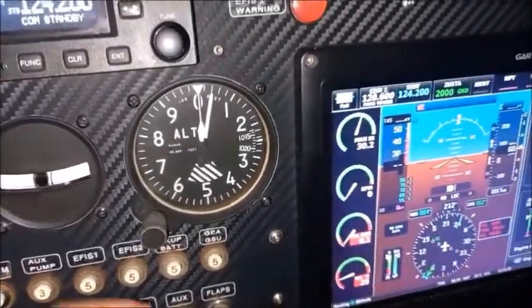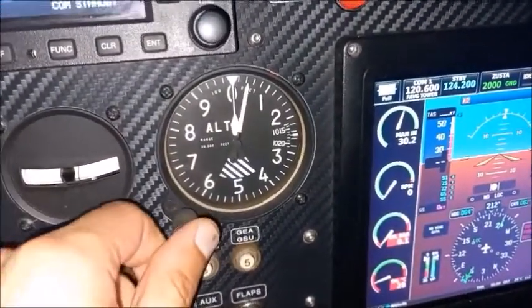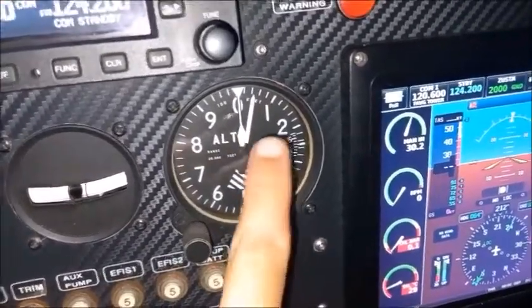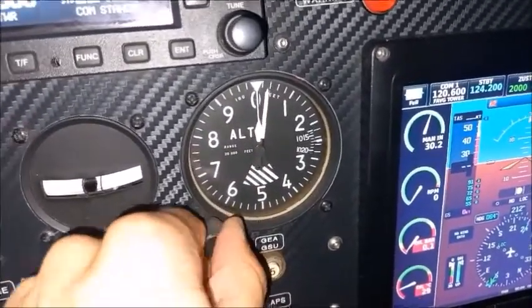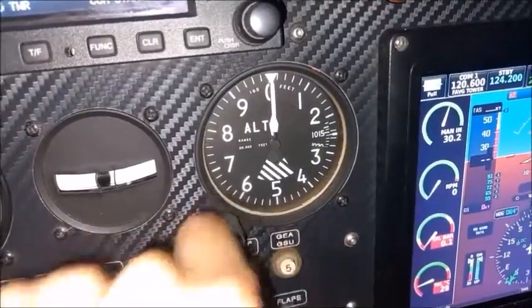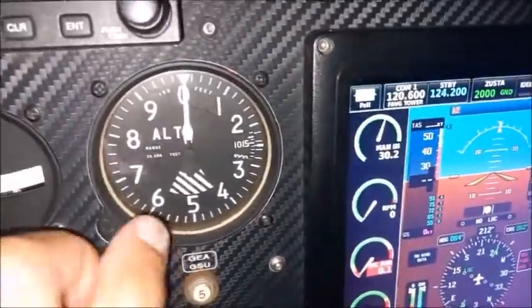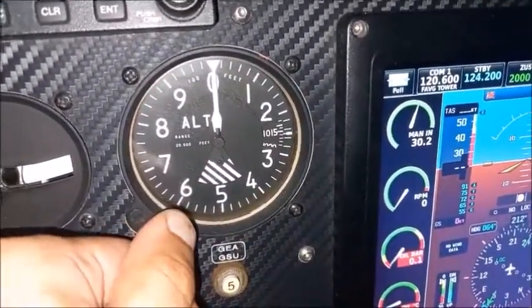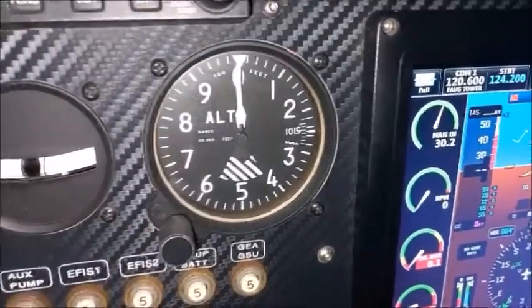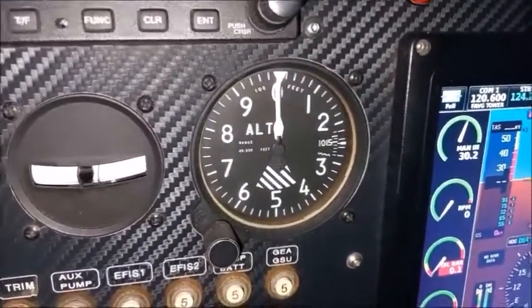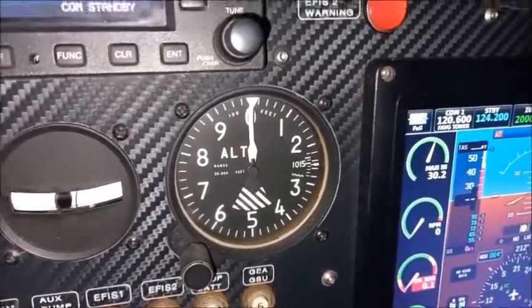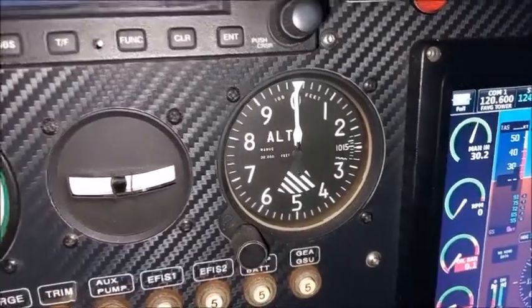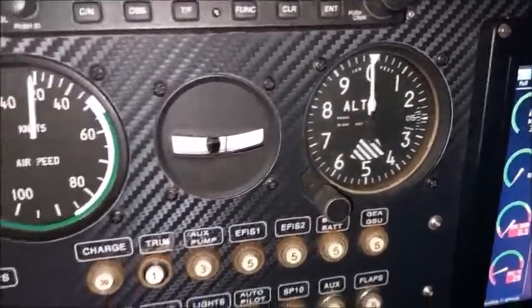So we need to calibrate this, and as we calibrate, you'll see over there we should be on ground level now at the moment. It just leaves us off over there, so we can turn that lever and it'll be on a 0 position over there. So as we turn this, that altitude setting at sea level will change, which is your QNH. And this is something we get the information for from air traffic control. When we go for the flight, we verify what it is, we change it over here, and then we are able to know exactly how high we are.